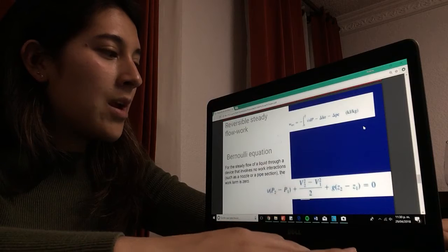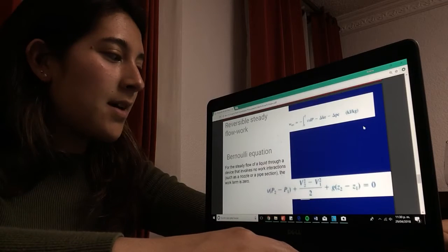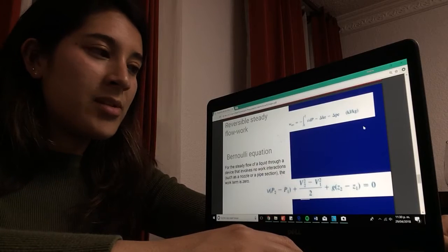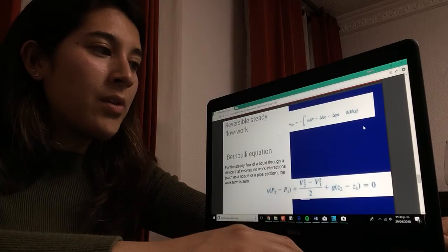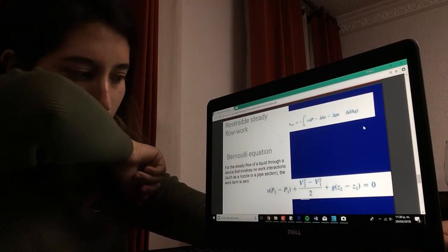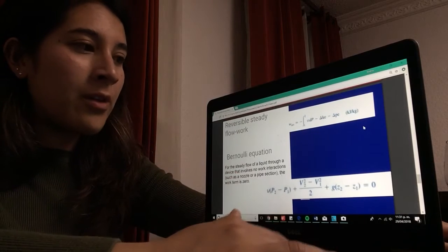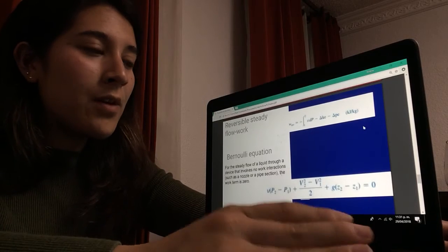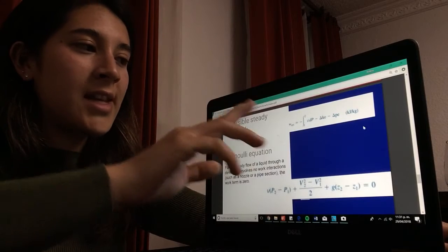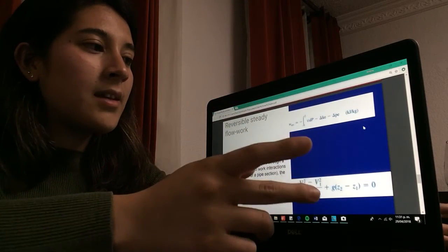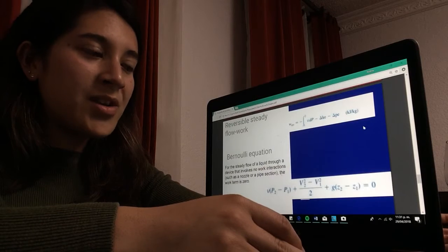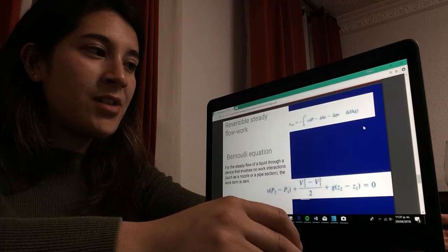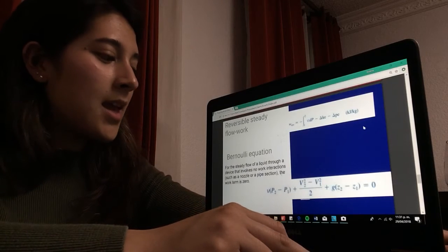And we're also going to have a reversible steady flow in these processes. So the work done is going to be equal to the negative of the integral between the two states of the volume times the difference in pressure, minus the change in the kinetic energy minus the change in the potential energy.